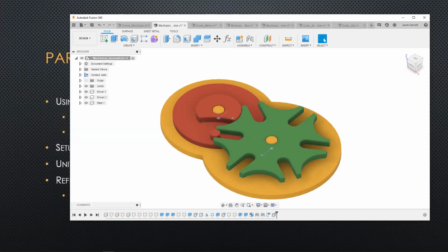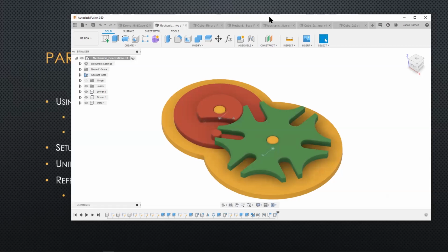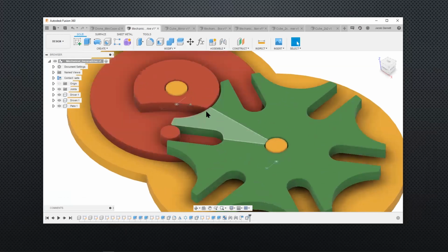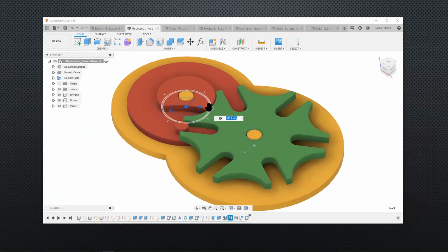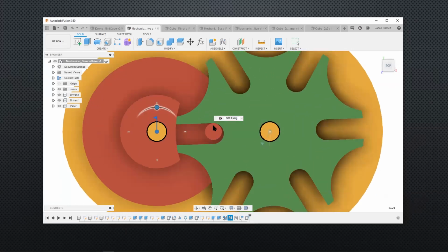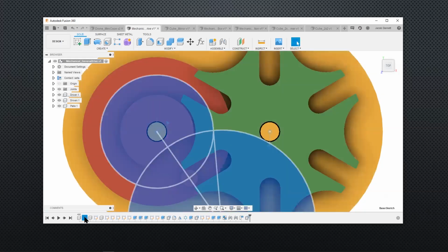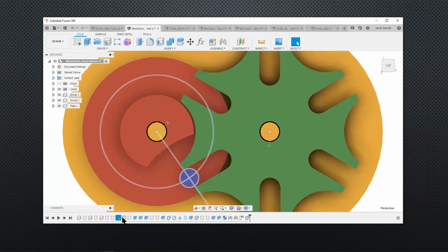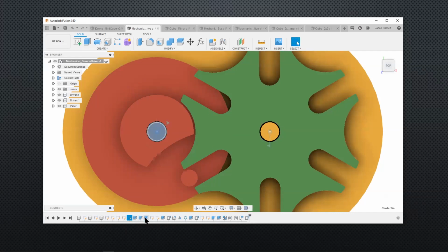Then let's see, units. Referencing other components. Yes, so our final thing, referencing other components. You can use parameters to do that. So in the case of this one, if I go to the maximum depth, which it doesn't like to show, this is a relationship which you could do with projecting. You could draw this out with everything projected in here. Instead, what you can do is you can have a parametric relationship between the two designs that I'm looking for the sketching here.